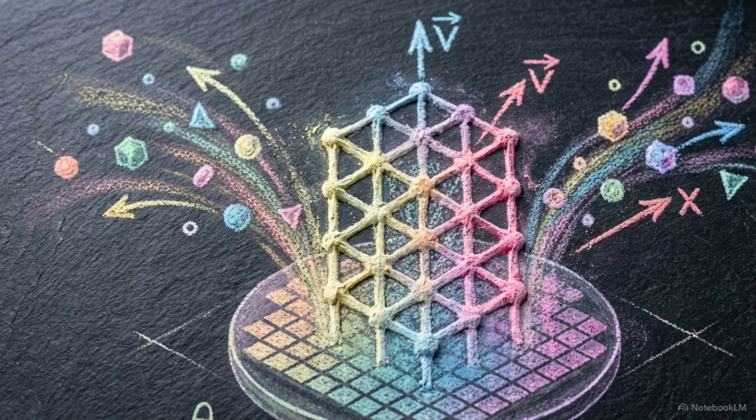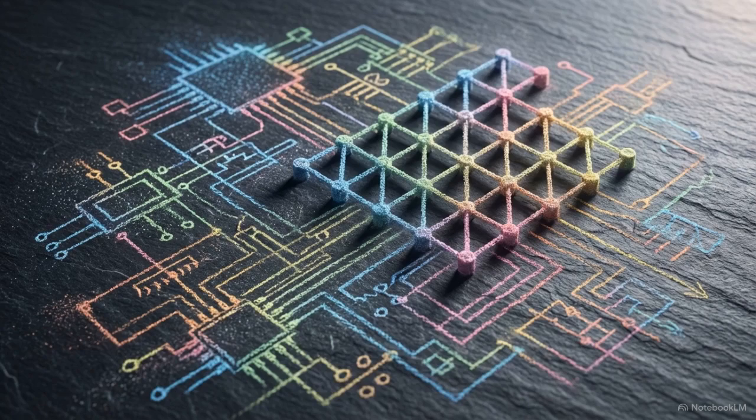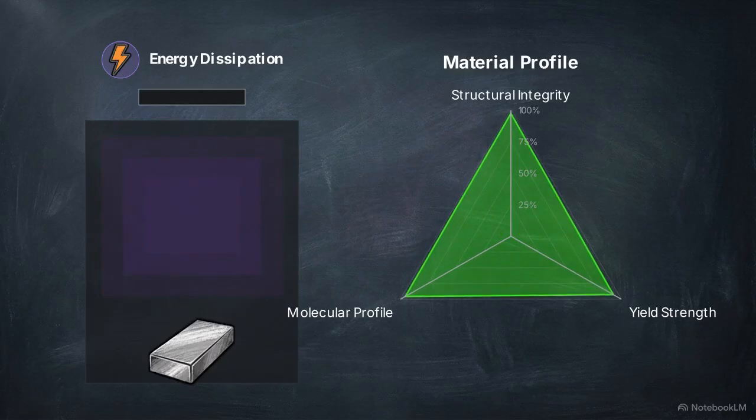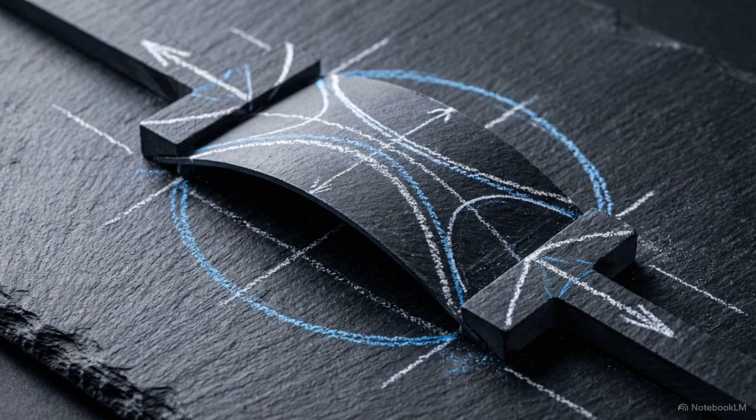In modern applications, PECVD is utilized to deposit pH-responsive polymeric thin films. These specialized polymers react to changes in acidity and serve as critical components in biomedical sensors and smart coatings. Manipulating the plasma parameters provides direct control over the physical and mechanical properties of the resulting inorganic films, such as their density, hardness, and chemical composition. For example, by carefully tuning the flow of silane gas through specific plasma parameters, engineers can deposit silicon nitride films with precisely engineered tensile stresses.